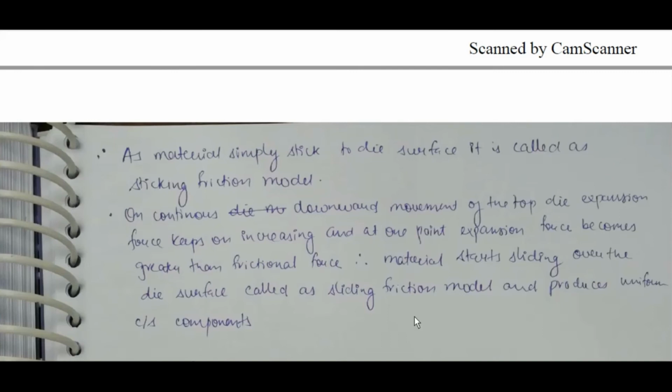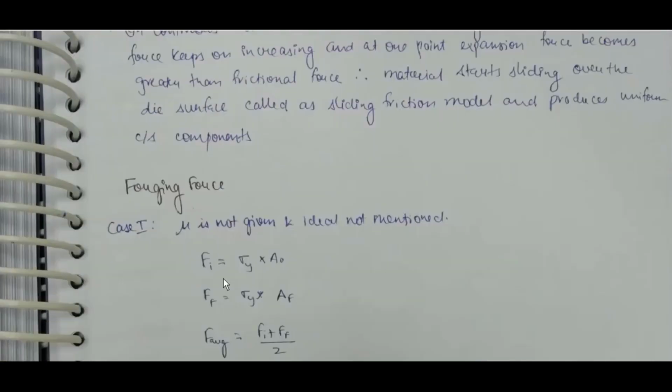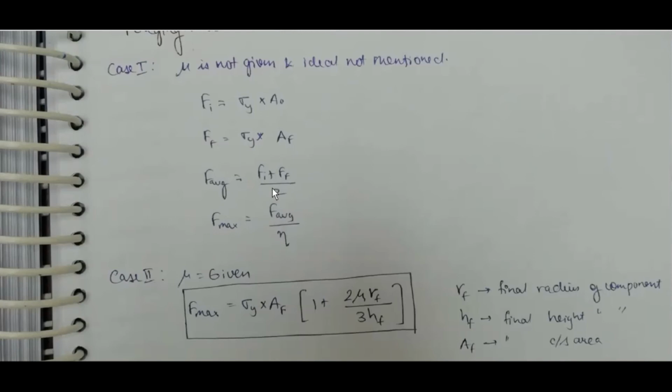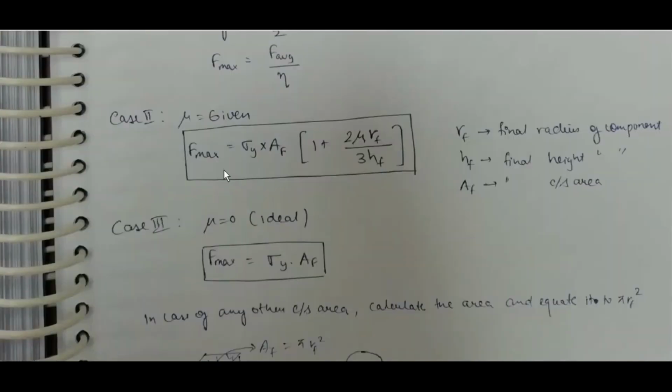The vertical walls of forging dies are made into an inclined surface for easy removal of the component from the die, called draft angle. Preliminary or preparatory forging operations. Fullering: distributing the material from the center towards the edge uniformly is called fullering operation. Drawing: distributing the material from the center towards the edge uniformly is called drawing.